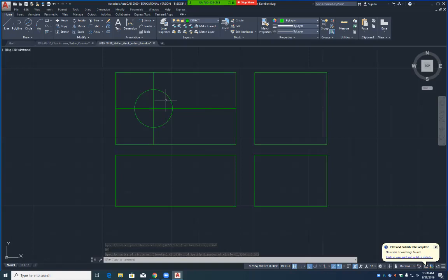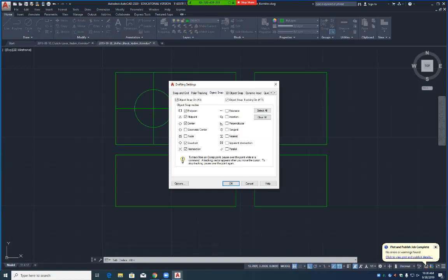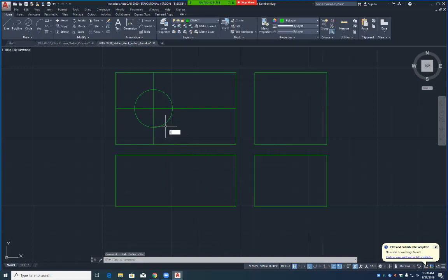And we're going to trim these out here. And we're going to change those to hidden lines right there. Now, as we start drawing these things, all I'm doing is using the line command and the space bar, and you should be about that fast. So, space.